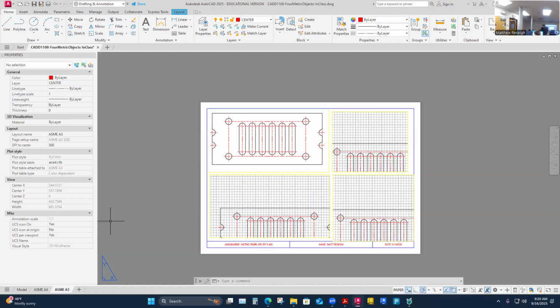Yeah, keep going, as far as you keep selecting those ones. Yeah, that's good. So you can select all these and change them. I just changed them to a line type scale of 5, so it's coarser. Here's the default 1, whether you're in metric or not. Line type scale is the pattern of the line type. And then there's a couple more you have to look at.